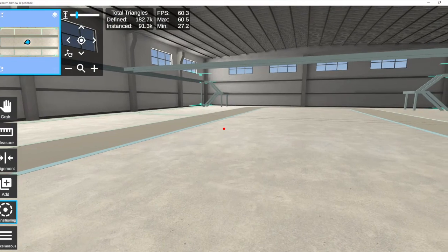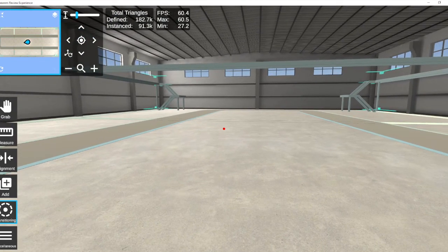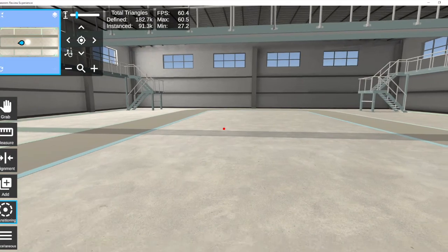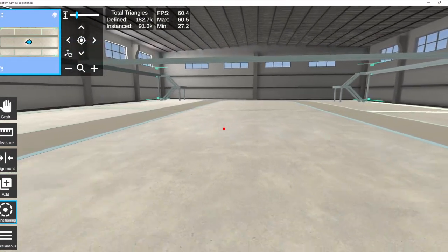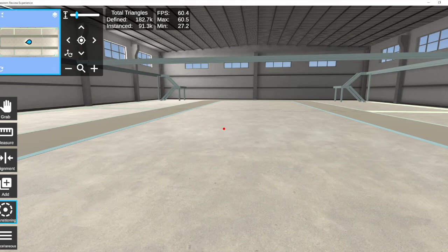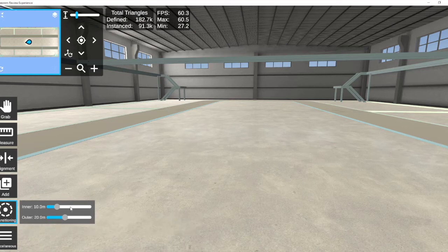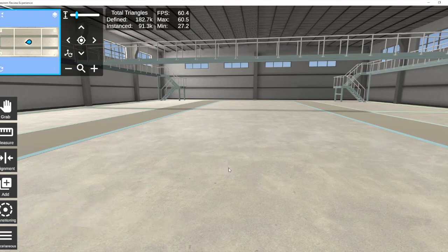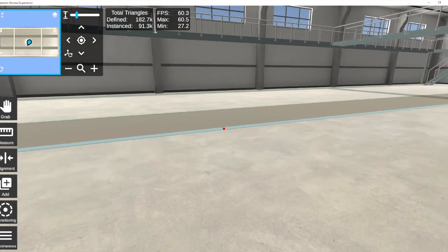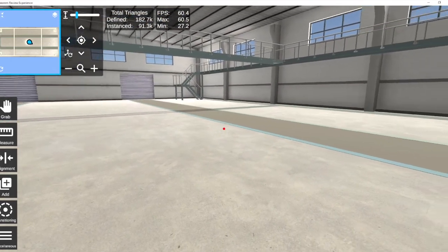So it's a scene of my factory, my layout, and you can see a bounding box visible currently. If I move towards it, more data appears, and this again is all about data optimization and data preparation. You'll see on the options here I've got transitioning on, and what that does is limit the data in the extreme views that's far away from you to optimize performance. So again, it's all about improving performance and ensuring that the experience for the user is optimum, it's prime. If I turn that off, you'll see that it just shows me all of the geometry. And obviously it's similar to what I showed you previously, but I'll show you a few more bits of functionality.